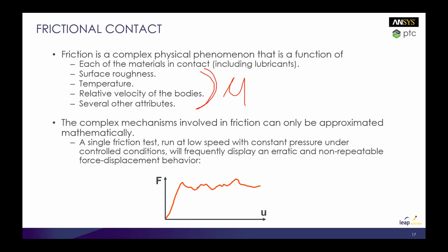Okay, so there are simple tests we can do to determine the friction coefficient between two bodies. A common thing that's done: you have the two parts, you slowly raise or pivot this surface, and when the block starts to slide, you can calculate the friction coefficient based off the sine of the angle of this plate here.